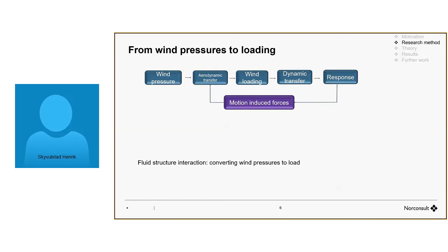Yeah, you could. It's basically like quasi-steady theory. You have the wind pressure in time series on the cross section, and you have a motion of the cross section, and then you get the actual force on the cross section. You take the force on the cross section, put that in, say, Abaqus, and then you get a new motion, and then you get a new force, and it's the same way. It doesn't matter what kind of bridge it is, basically.